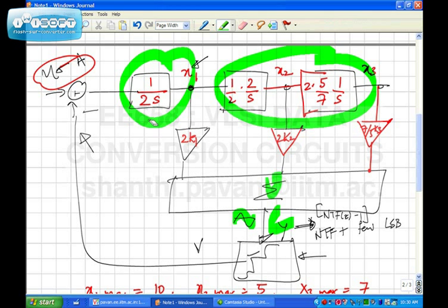Whereas this has to be very low noise and high speed, because this is basically handling a lot of high frequency components, because most of the high frequency shaped noise is at high frequency. This guy handles whatever, it's looking at filtered noise, whereas this guy is handling filtered noise which has been filtered twice. So the speed requirements of this op amp are much lower. Okay, so if you want to optimize power, you make this the best, these two cheap.